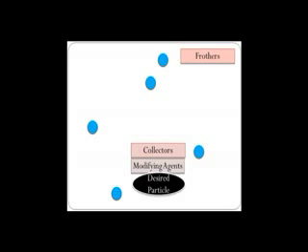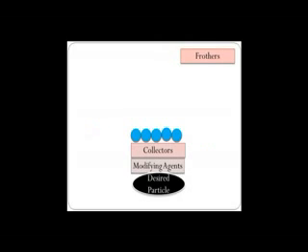Next, the collectors coat the modified surface and render the particles nonpolar. The nonpolarity is due to the dual polarity of the collector molecules. The polar end orients into the interior, while the nonpolar ends extend outward. Rendering the molecules micelle-like will allow for easier separation and allow the bubbles to stick. It is one of the important roles of the collectors to favor the adhesion of the air bubbles, which are essential for the floating action needed for separation.